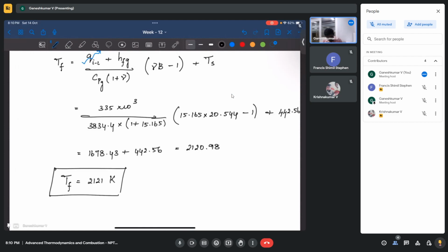But if you run n-hexane combustion at equilibrium, let's have a look at how much the adiabatic flame temperature would be. In the same table from which I have been taking HFG, there is also the adiabatic flame temperature. For n-hexane, we have a temperature of around 2273. Okay, so that's the equilibrium temperature.